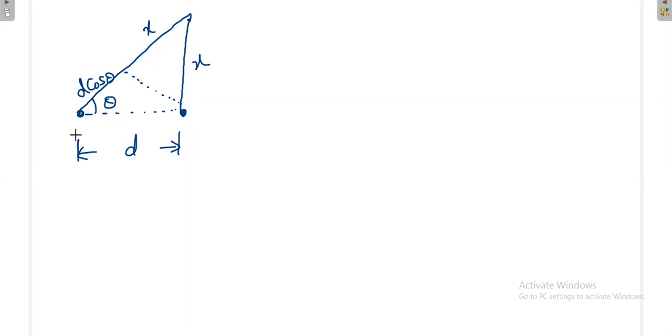Suppose you are exciting the antennas, each with current I. You provide a phase difference: the first antenna has 0 phase, and the second antenna has phase alpha, that's okay. Now, somebody tell me which wave will reach the receiver very quickly. You are exciting both antennas at the same time. Among these, will the wave from antenna 1 reach the receiver very quickly, or from antenna 2?